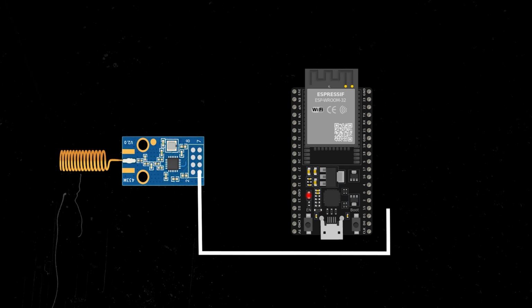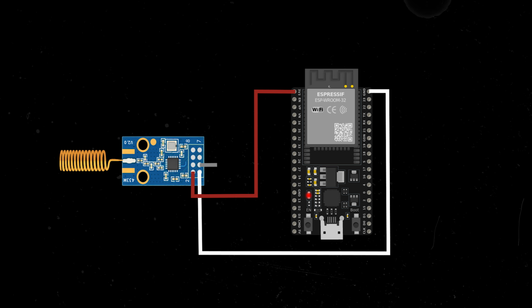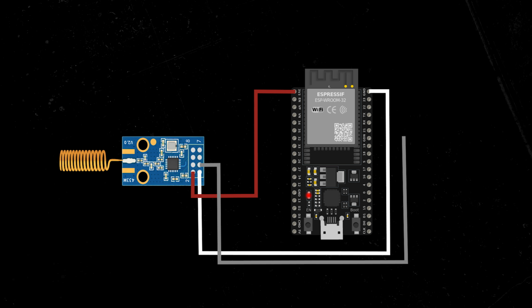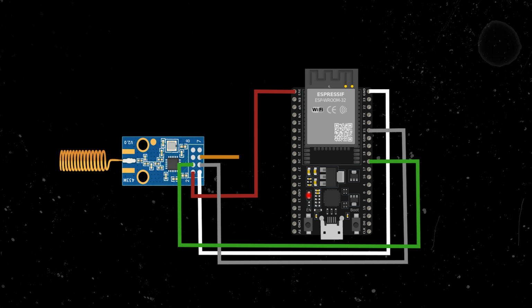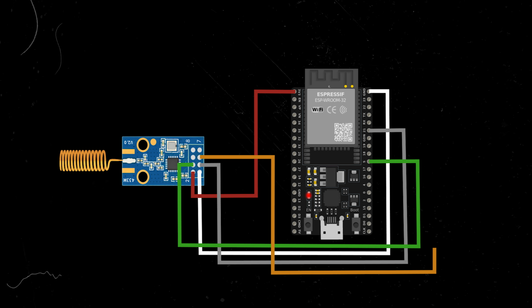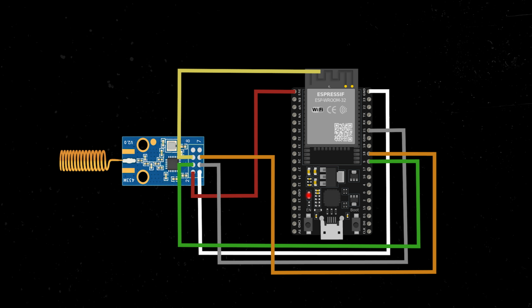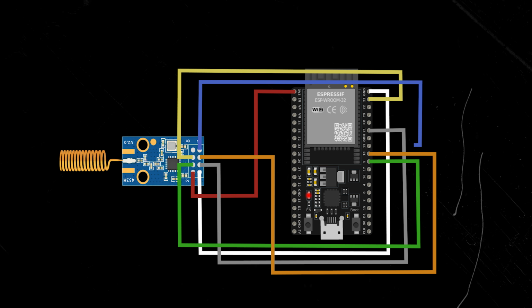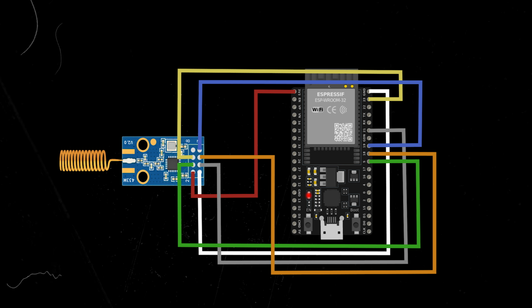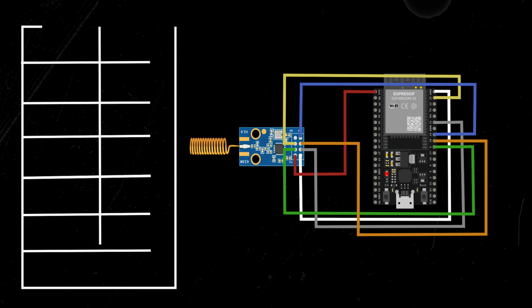For this project, I'm using an ESP32 powered with a CC1101 sub-GHz radio module. This will give me full control over the radio parameters like the timing, the deviation and modulation, everything the Flipper struggled with earlier. The wiring itself is actually pretty straightforward. The CC1101 runs at 3.3 volts only, so it connects directly to the ESP32's 3.3 volt rail with a common ground. SPI handles all the communication. Chip select goes to GPIO 5, clock goes to GPIO 18, MISO goes to GPIO 19, MOSI goes to GPIO 23. Finally, GDO0 connects to GPIO 21, which the library uses for precise timing and signal control.